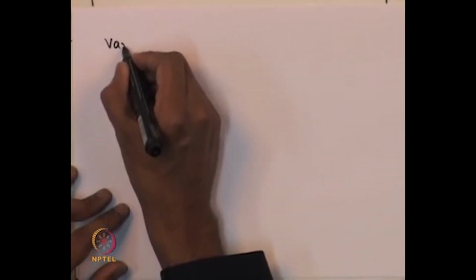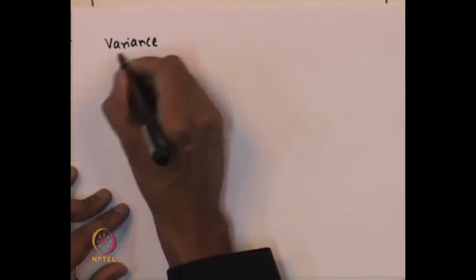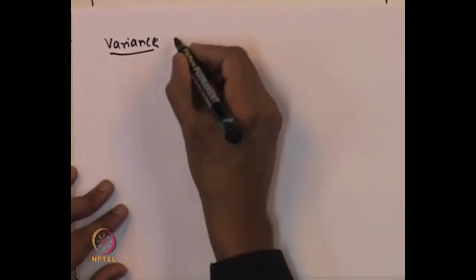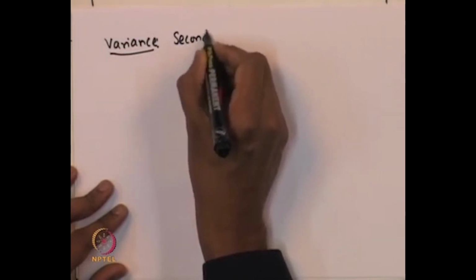fluid is flowing. So, are there other properties? We looked at mean residence time, and we also showed that the mean residence time should be equal to the space time irrespective of the RTD function, as long as the dispersion is negligible or 0, and also if the volumetric flow rate with which the fluid stream leaves remains nearly constant. So, are there other properties? And the answer is yes, there are other properties. We can also estimate the variance of the distribution, and that can be obtained using the second moment.